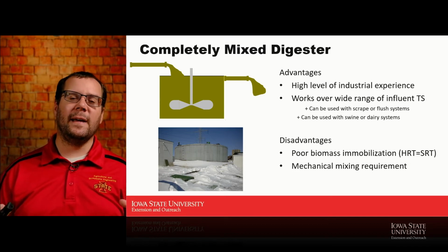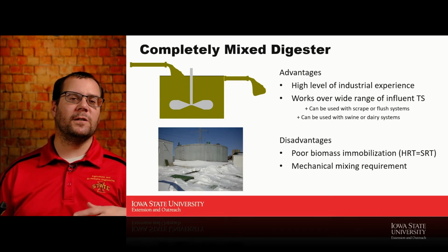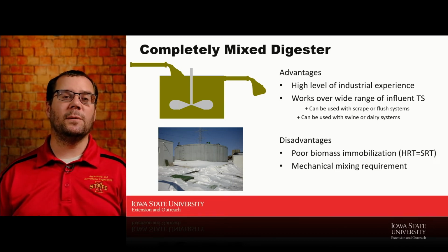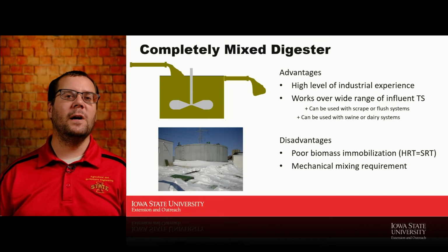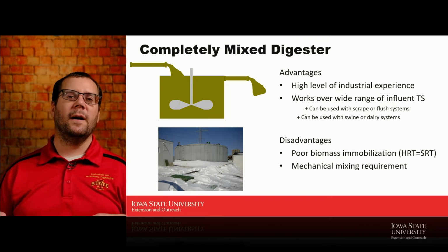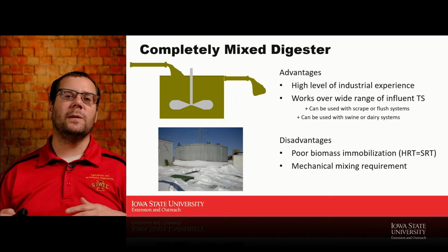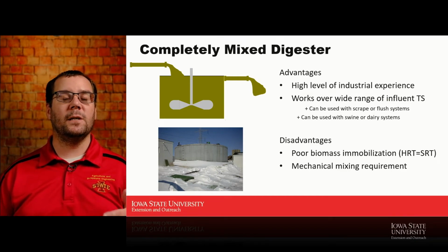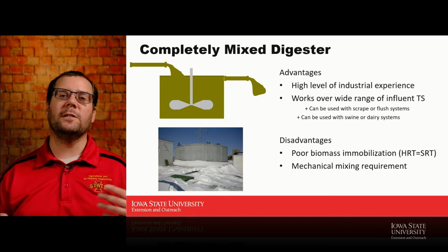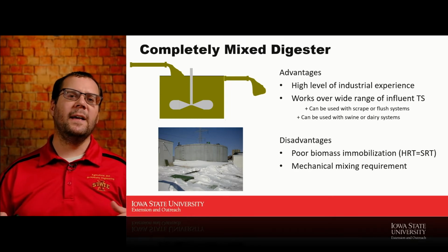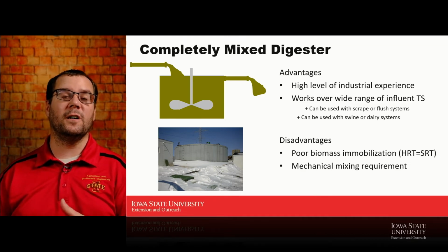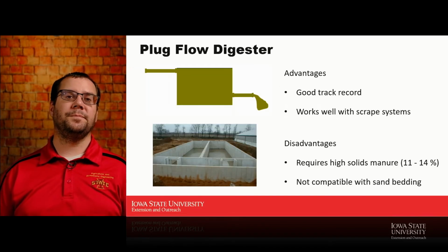When we get lower than that, oftentimes it's very watery, and we'll look for something like a fixed film digester, which I'm not going to talk about much because that tends to be something we see more for sugary waters and food processing rather than agricultural situations. And the other one is, in this situation, we aren't doing anything to help our biomass stay in that tank, right? So our bacteria are going to build up to a certain level, and then they outflow at about the speed that we're growing them. And unfortunately, that slows down our reaction rate some, but it does make the process relatively easy to manage and doesn't require other monitoring to really make it work.